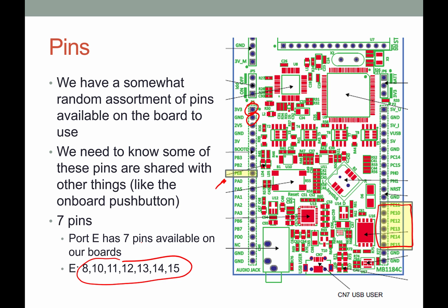So you'll have a breadboard just like you had last week. This whole discovery board is sort of placed in the breadboard where you have these PE8 pins, as well as your ground and 3.3 volt. You'll need to put those in there, and you will have to hook things up based on those particular spots.